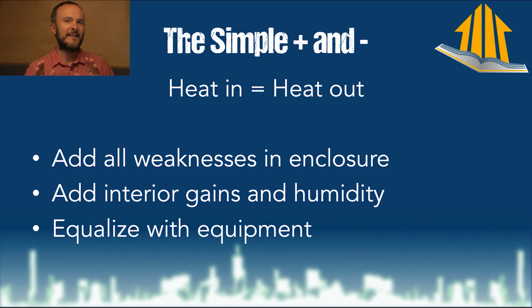So some of this is, the model needs to be proven out by the actual performance of the actual house in real life after you've done the model. That's why you want to work with somebody generally who's done quite a bit of these. So all you have to do is just add up all the weaknesses. That means anything that's a window that's not very insulated, any of the air leakages that you've got, any places where insulation is missing, things like that. And then the computer tells you how much you need to make up for that. Now, you will be using a computer for this.